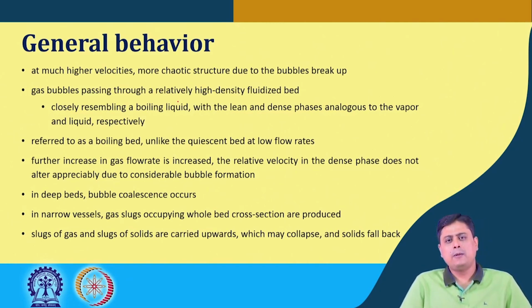And what happens? These slugs of gas and slugs of solids are both carried upward, and these may collapse, which leads to fallback of the solids at the bottom of the bed in a downward motion. So, the recirculation of the solid particles is very prominent in such cases.